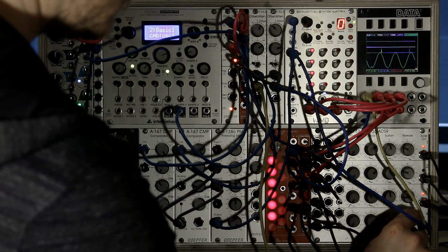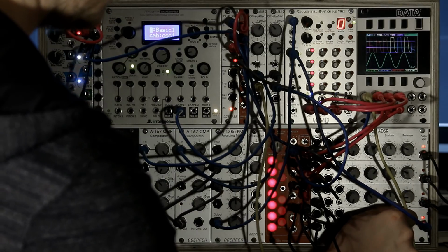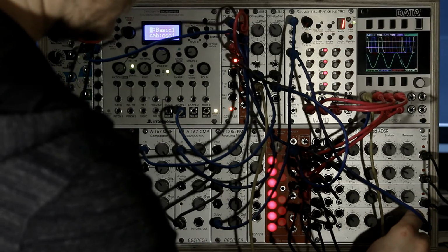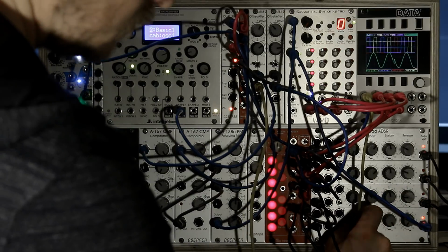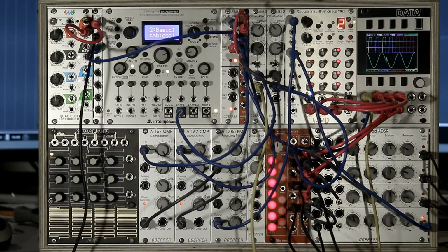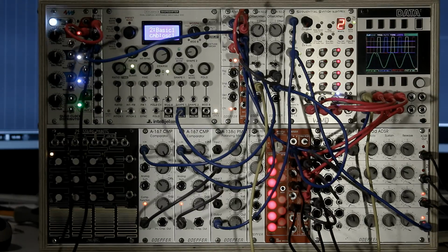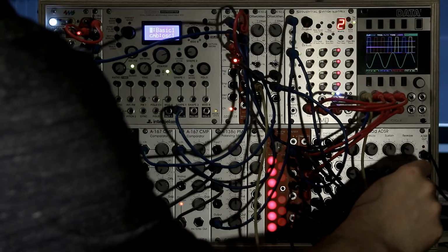Trigger delay didn't fit into this case, so I will use an envelope generator to offset this trigger slightly. You can see the changes I am making on the scope. The rising edge of the clock has some slope now, so it takes a bit of time to get to the level that would be considered a trigger level. I have set decay and release to 0 and sustain to full to keep the level at maximum. And our sync problem is gone now.